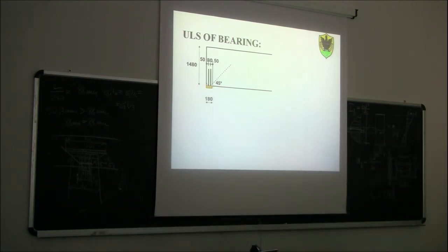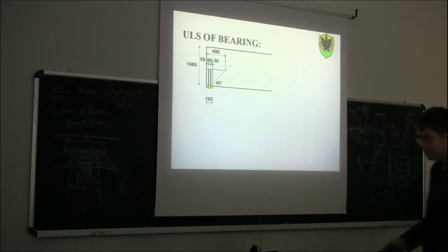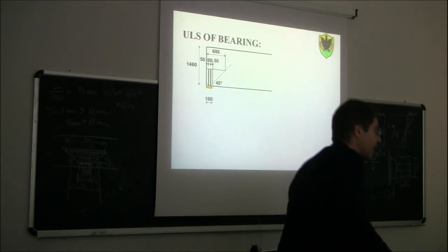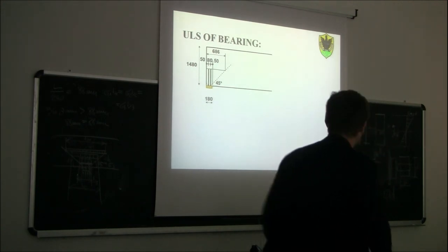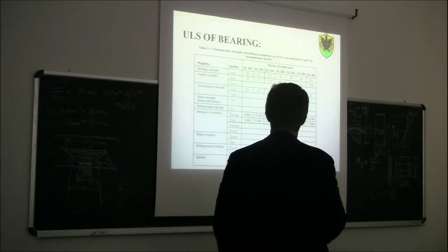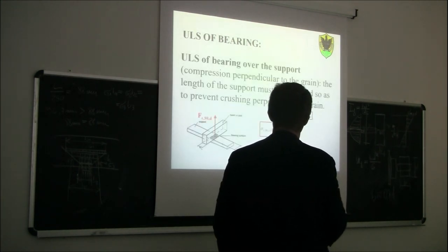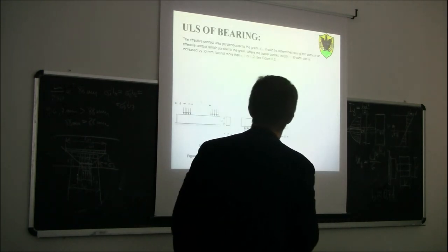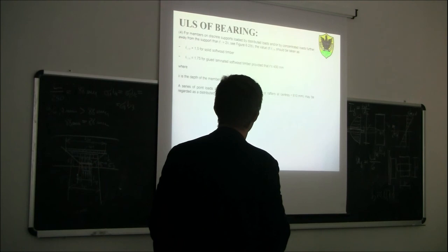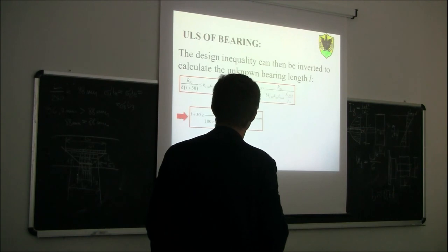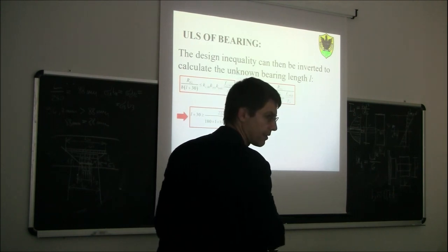So you see in this case we have one line going up in this way, 45 degrees, the other one goes up 45, then here it cannot go any further because the beam is finished basically. So since our minimum distance in order to make the verification satisfied is 686, in this verification we need to take outside the 30 millimeters of the effective width. So if you go back, this is the length that we need to find, 386.